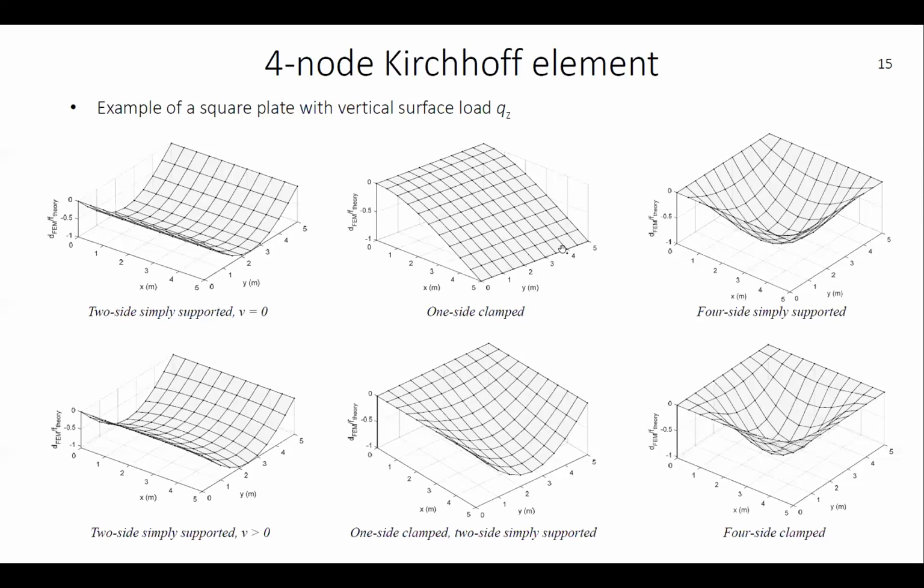If we have added boundary conditions along the x axis on the edges, we will have one side clamped, and in this case, two sides simply supported slab. And here there are also theoretical equations for how to solve this. But using these current element formulations, we are underestimating the displacement using the finite element approach. So it's slightly overstiff compared to what this theory says.